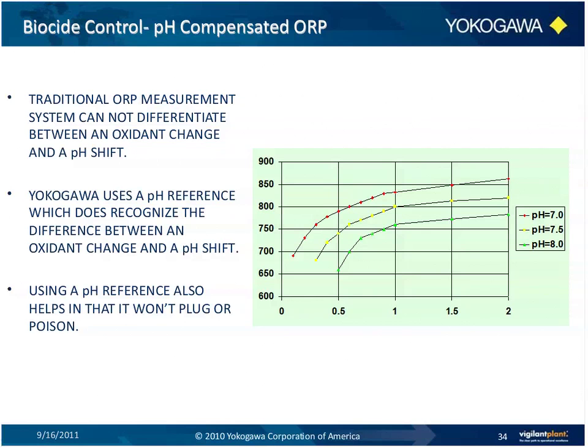Since the pH electrode is acting as the reference electrode, the stable millivolt value that it generates will shift at the same rate as the millivolt change caused by changes in pH. The advantages of using pH compensated ORP are that the process control is more reliable, since the millivolt value given depends on the reagent concentration and not on the pH, and there is less maintenance because the measurement doesn't require a reference cell that could lead to potential junction troubles later on.